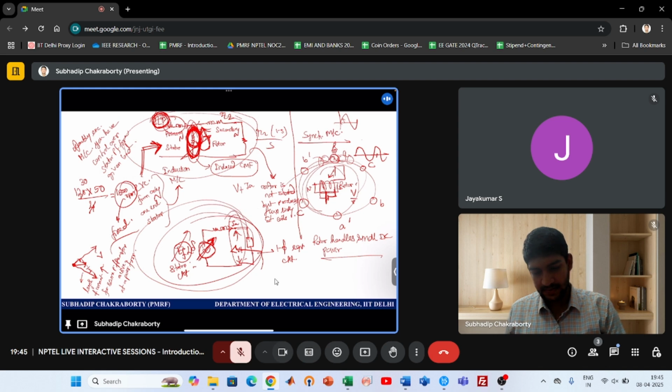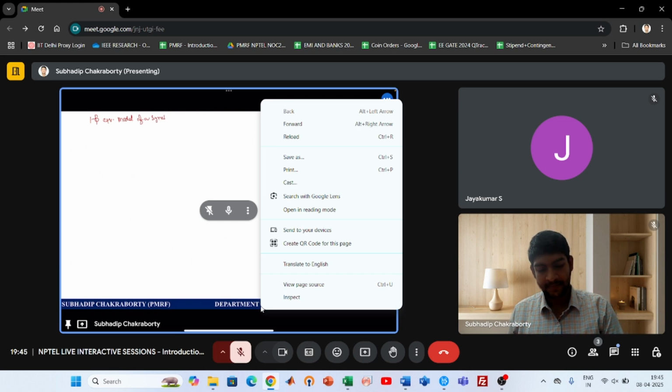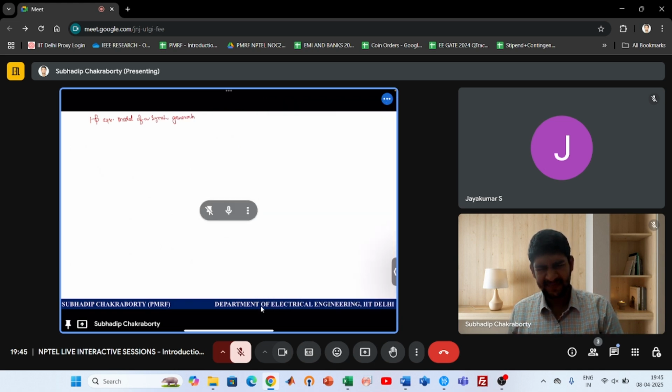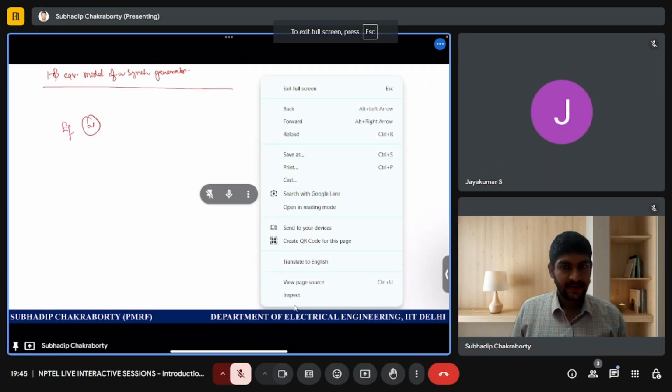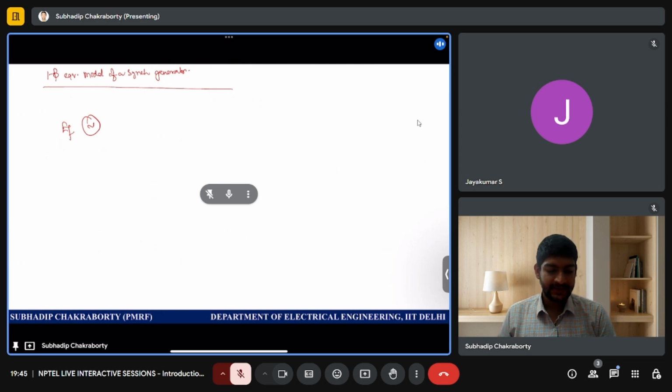Yes. So what is the model? Single phase equivalent model of a synchronous generator. I told you that we have some voltages induced, EF. So this is the open circuit induced voltage by the rotating field coil or the rotor, which is nothing but an electromagnet and induces some voltages. And we have XS, synchronous reactance, and RS, forming ZS.